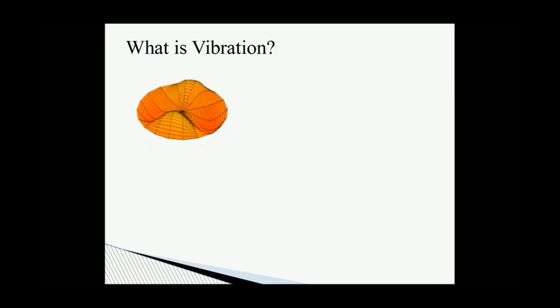Now, when you start talking about deformation, you start going into modal analysis, which is a related but different field from vibration testing. It is more on the engineering side of structural testing, and we will go into more detail on modal analysis and modal testing in a later presentation, but right now we're just going into the basics of vibration testing and vibration terminology and application. But I wanted to get you familiar with some of these terms. And to get you a little more familiar with modal analysis, we're going to go ahead and look at a mode of a cantilever beam.